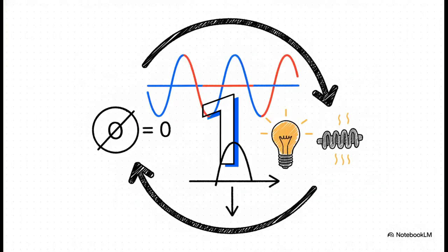So, the crucial takeaway for our resistor is the result of that cosine calculation. It's exactly 1. Think back to our synchronized dance. The phase difference, theta, between voltage and current in a pure resistor is exactly 0 degrees. And if you plug that into a calculator, the cosine of 0 is exactly 1. This means the power factor of a purely resistive circuit is maxed out at 1. It is literally 100% efficient at converting that electrical energy into heat or light because the voltage and current are pushing in the exact same direction at the exact same time.